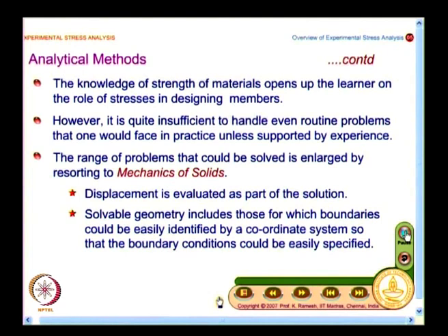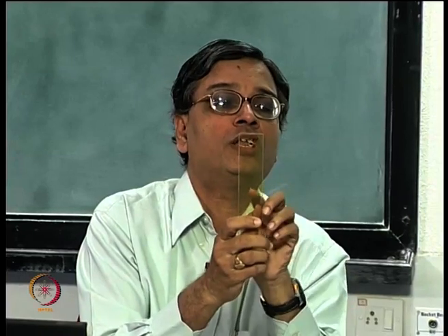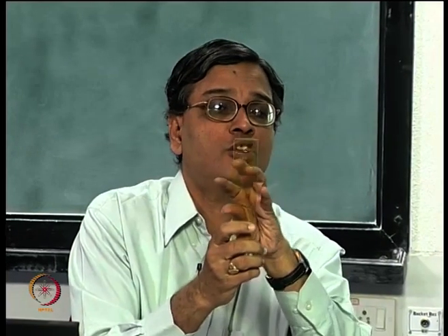So, when I go to theory of elasticity, where I am able to idealize, I look at a situation where I remove the restriction on displacements and I evaluate displacement as part of the solution. Even there I need to have infinite boundaries for a problem like this, only then I will be able to solve. Mathematically the distances are far away, but physically it could be a very small hole. This closely resembles it, and this solution is possible. And plate with a hole is a very important problem.